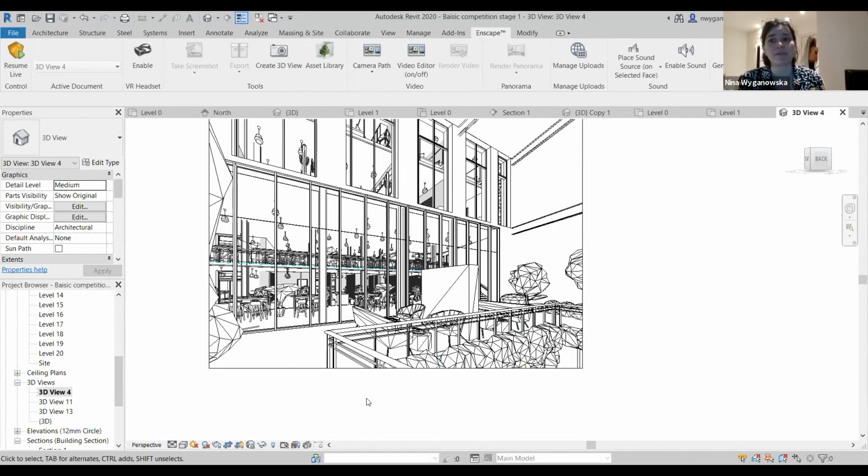The problem with Revit is that if you use different walls and you want your elevations to be extremely colorful and have different paneling on them, you have to cut your walls into pieces, which is extremely annoying, and then disallow them to join. That allows you to do different panels within your wall and cut different profiles, which is annoying to do, but it is possible.